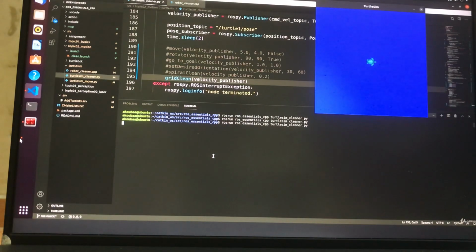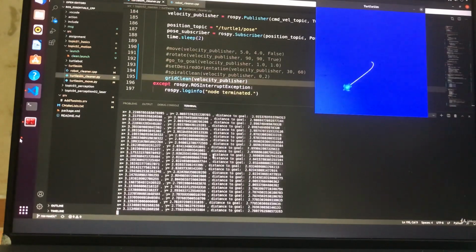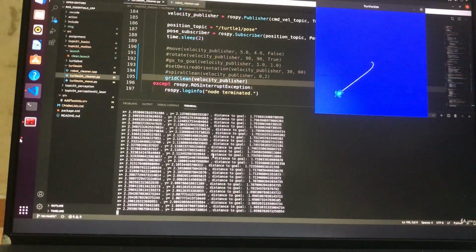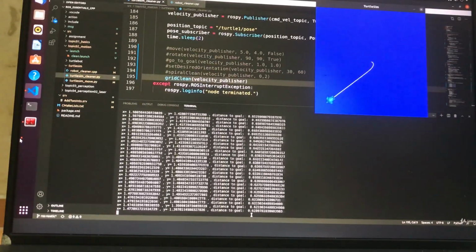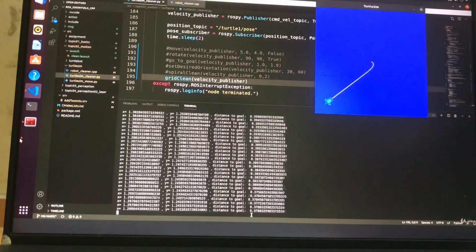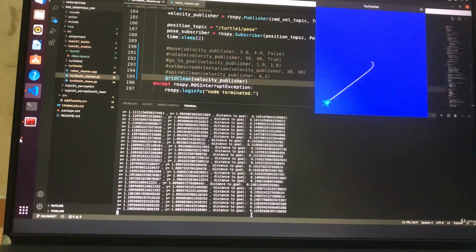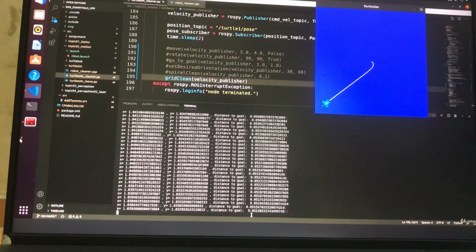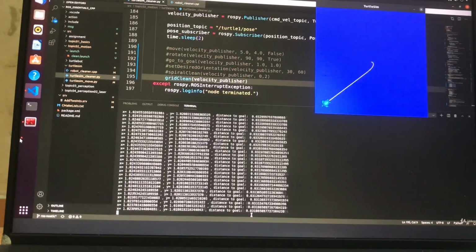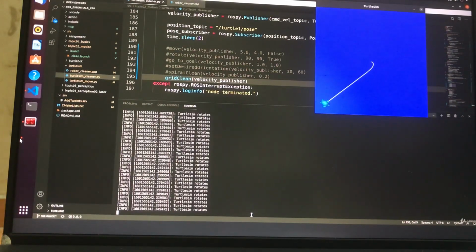Okay, we can now activate the grid clean method, and after executing, you can see that the robot first starts from the location 5, 5, and it will go to the location 1, 1 that we have specified using the go-to-goal behavior. This is the first method that will be executed, and when it reaches the goal location, it will set the desired orientation to 0, so it will rotate so that it will look in this direction. Now the robot starts rotating to go to the absolute orientation of 0.